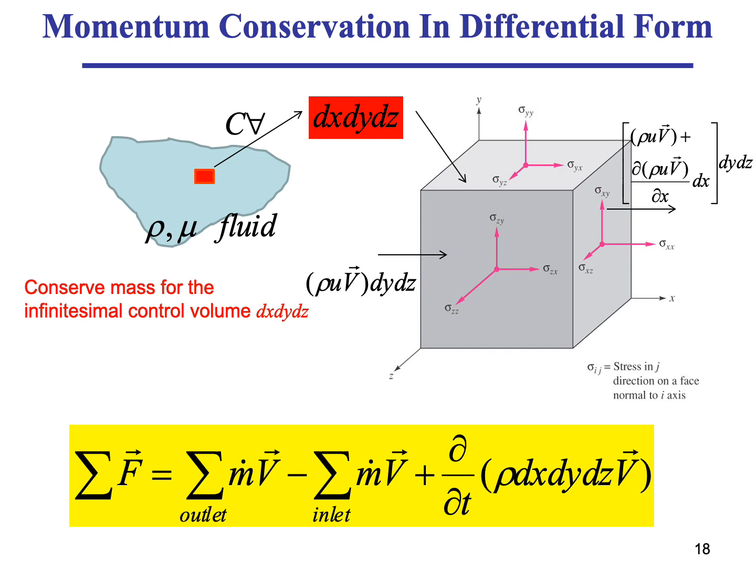And if you see, the neighbor to this face exerts 3 orthogonal forces or stresses. You have 1 normal stress perpendicular to the area and 2 shear stresses. What I would like you to pay attention to is that the stress sigma has 2 indices, 2 subscripts. Here it's sigma zy. The first index refers to the face z, and the second index refers to the direction of the stress. In this case, it's pointing upwards. So you can guess here, sigma zx is the stress on face z in the x direction because it's pointing in the x direction.